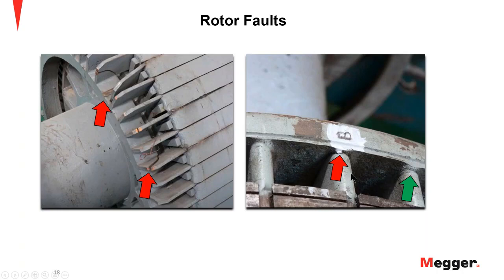And then this one here is pointing out brazing. When the shorting bars are being brazed together, they're actually looking at this cold weld here. It doesn't look like a smooth melted metal weld, and that's where we marked it for a brazing issue. You can tell from this side that this is a good weld and this is a cold or soft weld, and this can cause issues. You can find this out by testing with different pieces of equipment.